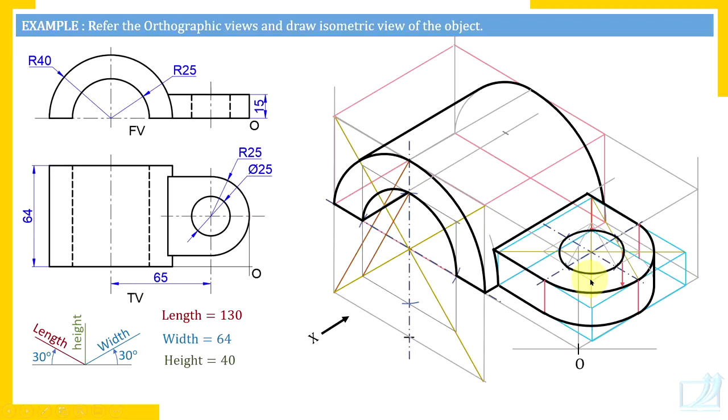Shift its center 15 millimeters downwards, because that opening is 15 millimeters. And from this shifted center, draw the longer arc here. If at all any portion appears inside the upper opening, then that portion of the arc you should make dark. So I made that small portion of the arc dark because it appears inside the opening. And this is how the drawing is complete.